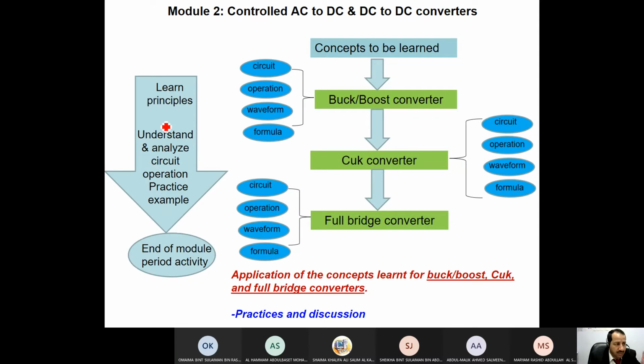We mentioned that we have DC input, which could be anything: rectifier, solar cell, battery, and we converted it into another DC, either greater than or lower than the input. Here, let me say 10. I can make it 15. I can make it 5. I call the lowest value the buck converter, step-down converter. And the upper value, I call it step-up converter, or let me say boost converter.